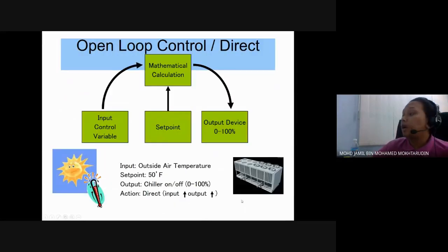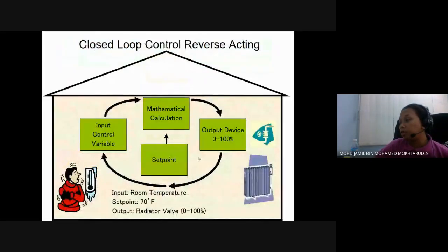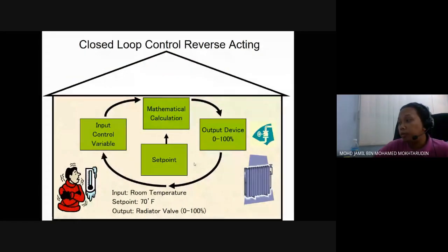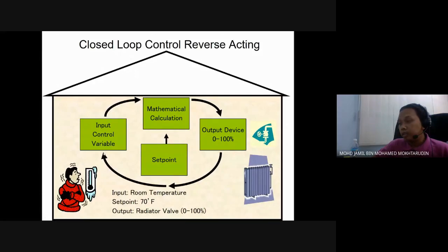So you have learned about open loop systems and closed loop systems. An open loop system basically has no sensor that measures the output and compares it with the input. So that's an open loop system. Meanwhile, a closed loop system has an important element, which is the sensor that measures the output and compares it with the input, and then tries to make sure that the output is within the certain range required, or that you desire.